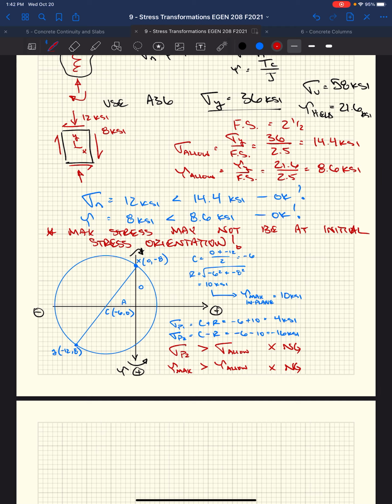And if we feel really good about it, we're going to use a lower factor of safety, right? The airline industry is a big example of that. If you used a factor of safety of 5 to create an airplane, it wouldn't be efficient enough to get off the ground. So you end up refining that analysis, feeling really good about the loads you impose and the analysis methods you use to calculate capacities, and you get the factor of safety down to like 1.5.